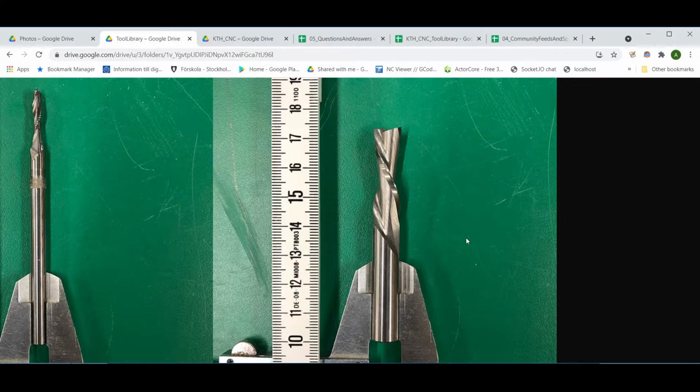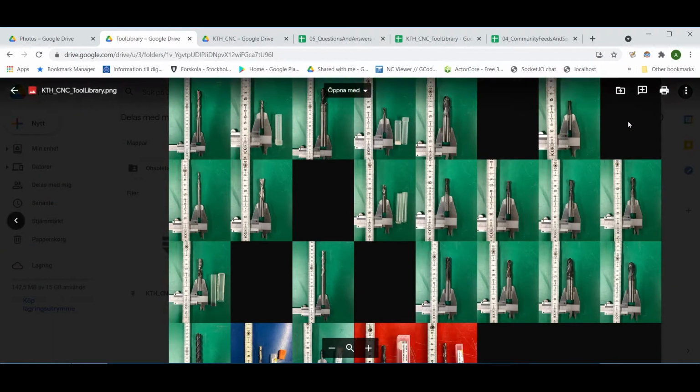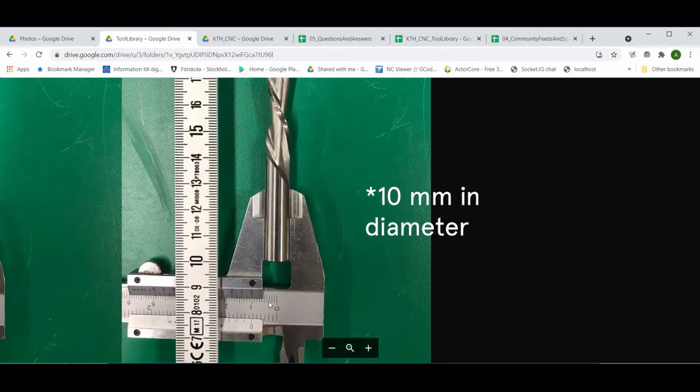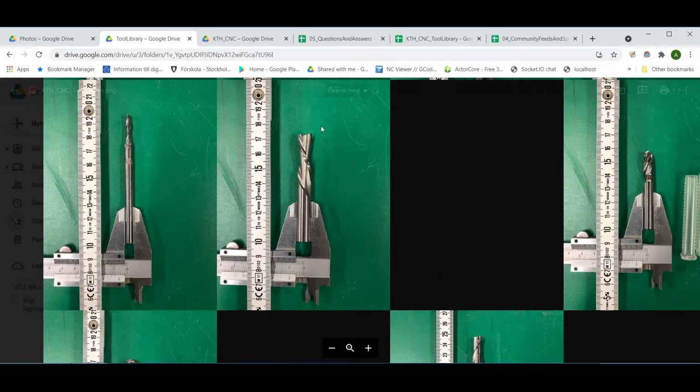This is, like said, a disadvantage when it comes to the extraction of milled material. That which otherwise would have been more easily extracted by the dust extraction is instead pushed down into the material. But the advantage is significant when milling these thinly layered materials such as plywood, since it does not leave such a significantly frayed edge. This tool in particular would be, if this is 8, 9, 10, tool number 10. Since it is a 10 diameter tool, I deem it a very good candidate for our roughing toolpath.